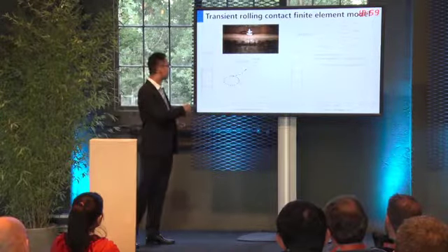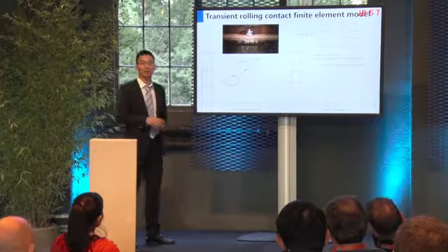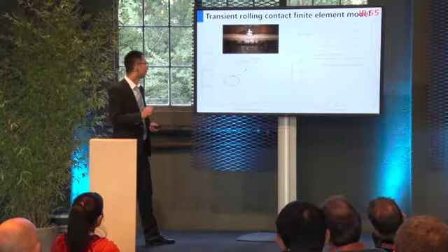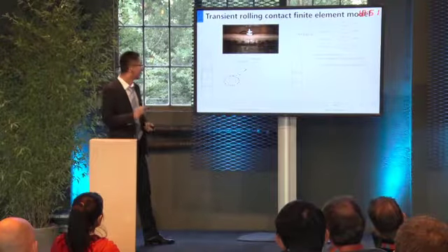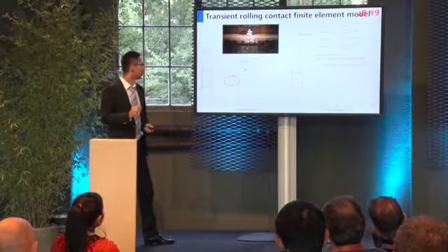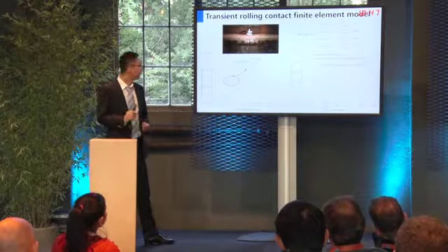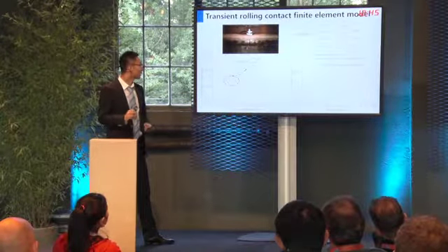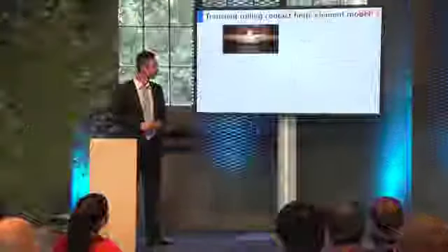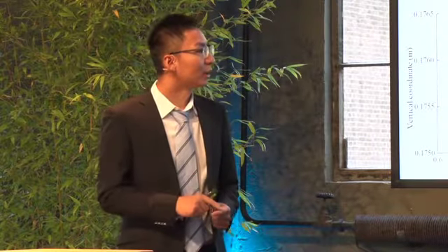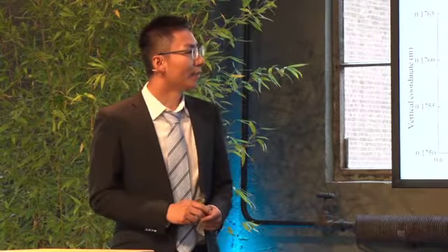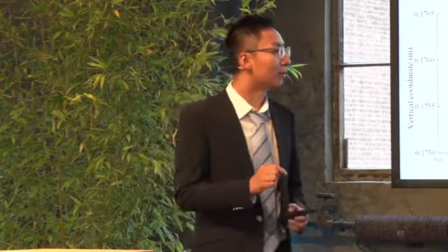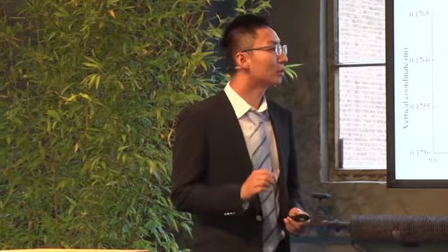The lower 2 figures show the geometry of the rail corrugation applied in the simulation. The left figure shows the geometry along the longitudinal direction. The corrugation is simplified as sinusoidal in shape. The right figure shows the cross-section of the corrugation, and the max depth of the corrugation appears at the wheel-rail contact central point.